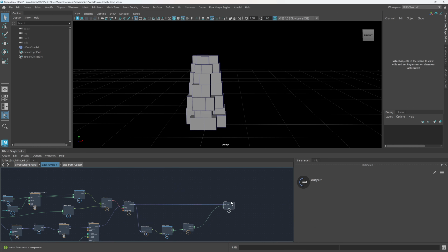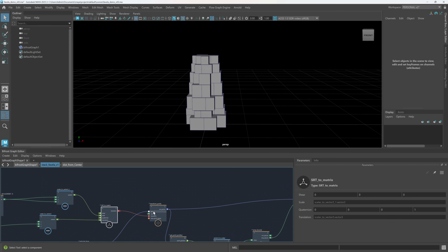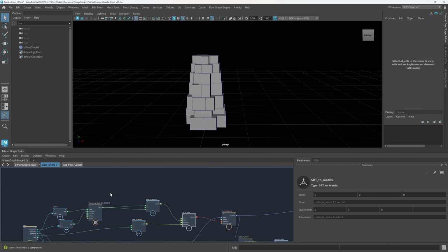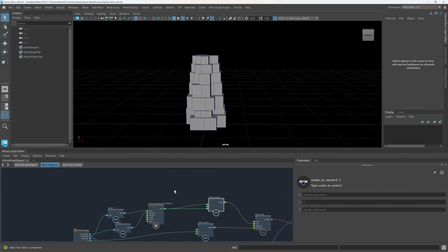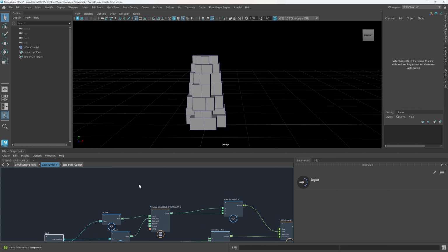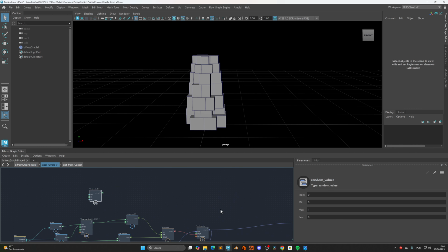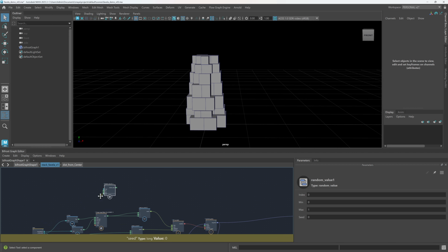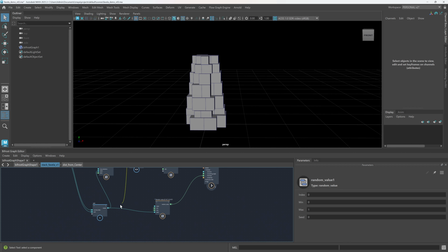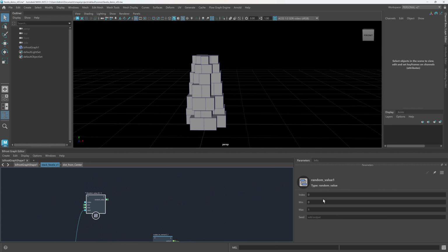So I'm gonna complicate things a bit in here, but you can totally just feed a random value to the quaternion in here with the necessary conversion nodes, and it will be all right. But again, I'm gonna complicate it a bit so we can possibly learn something new. So first of all, we'll start with a random value. I want a random value based on the seed. So we'll go in here, and I want a random value between 0 and 1.